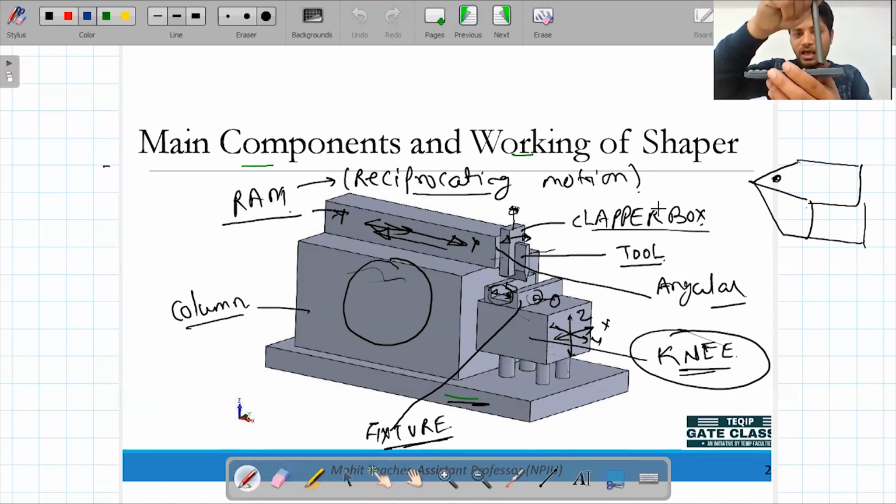So now when it is coming back, only a very small portion, not equal to the depth or lesser than that, is coming in contact with this tool. So when it is returning, only a small amount of the workpiece comes in contact with the tool, okay. So it can create a problem of surface roughness, okay. There is a chance that while coming back it can remove the material, but it happens very little, okay.